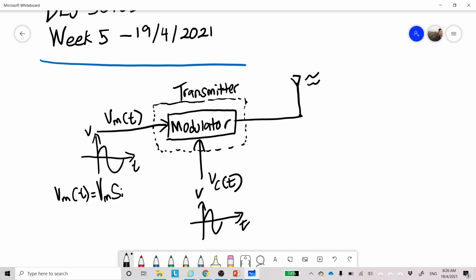When you want to derive the AM signal, you need to derive from the envelope waveform, which is V in bracket VC plus VMT close bracket multiplied with sine 2 pi FCT. So that produces VC sine 2 pi FCT plus VM sine 2 pi FMT sine 2 pi FCT.